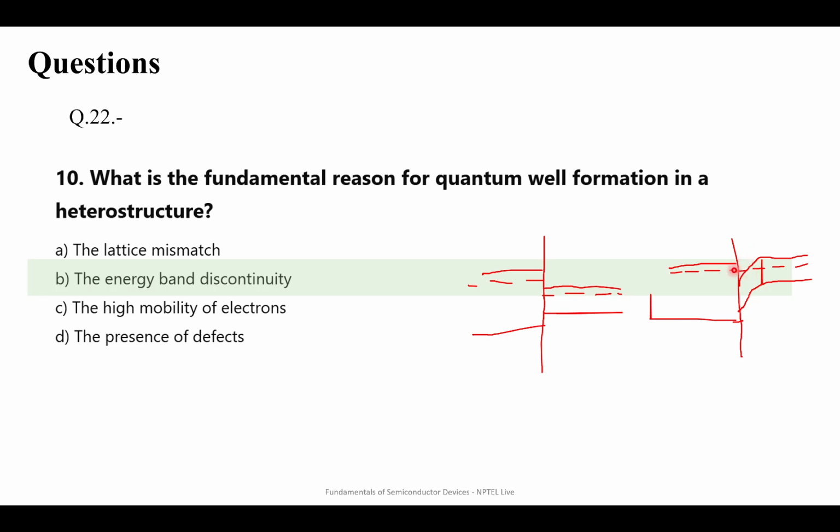So this creates a potential well here due to band bending. And my Fermi level, you can see, is above this potential well. Yes sir. It's above, outside the band gap, right? This is like strong inversion, sir. This is even beyond strong inversion.